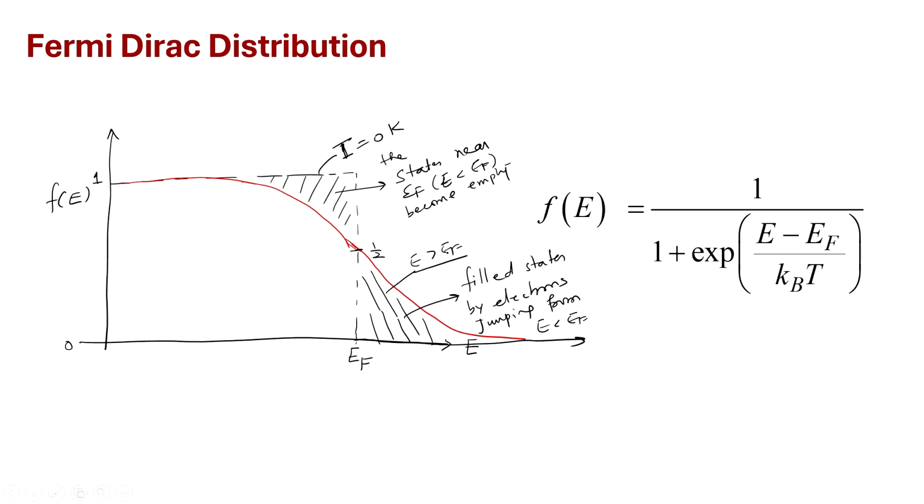Okay. So, what it tells you is that it is not all the electrons which take part in conduction. It is only those electrons which are in the vicinity of Ef that take part in conduction. So, it is electrons within this band, and this is a narrow band. Of course, for the sake of illustration I have exaggerated it, but otherwise it will be even narrower.